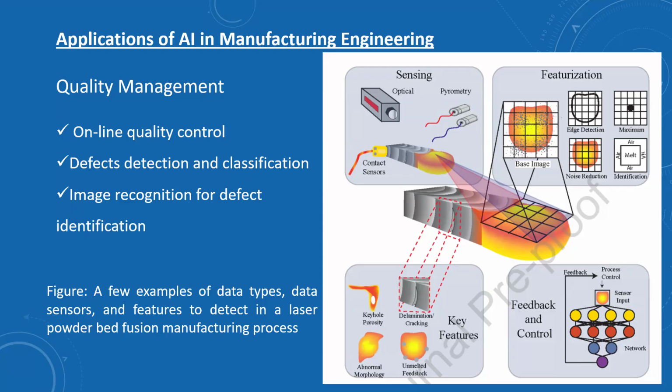Most of the defects are in the bottom layers, or the middle layers, of the additively manufactured components. So it is practically very difficult to detect the defects by naked eye or by using experimental techniques like optical microscopy. You have to go to a microscopic level, then only are you able to find those defects.